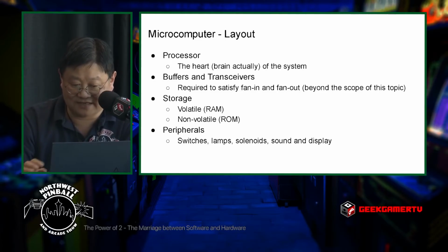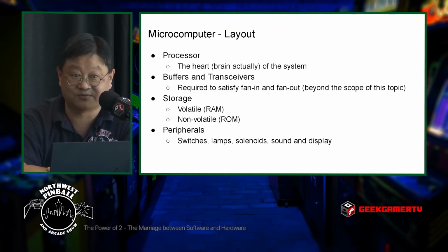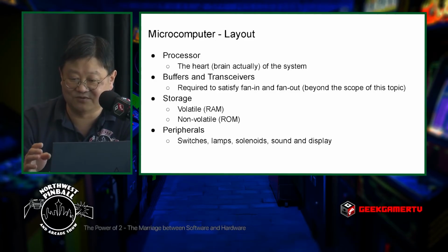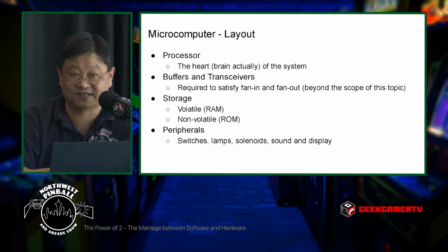And then as part of a machine, you'll find that there are also peripherals. Switches, lamps, solenoids, all controlled through, in System 11, peripheral interface adapters. And in WPC, controlled on the power driver board itself with all the transistors there. WPC will be touched on very briefly, but I think the focus of this you'll find is System 11 because it's easier to understand.